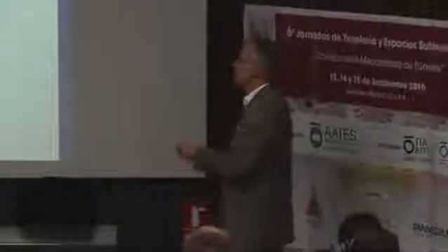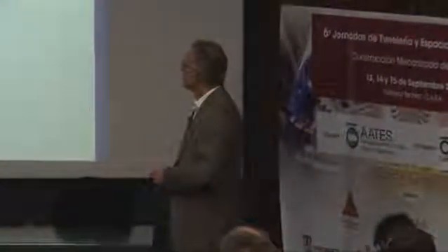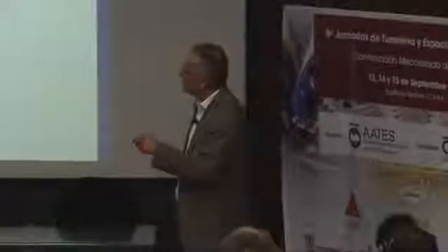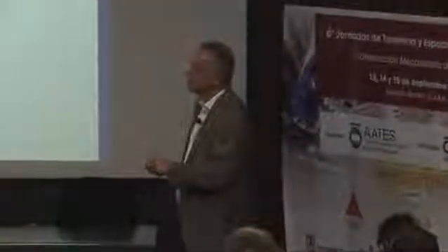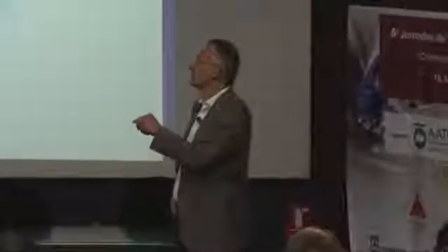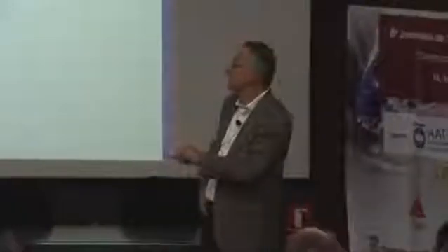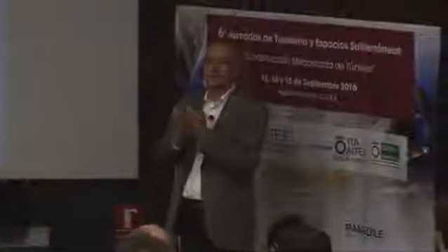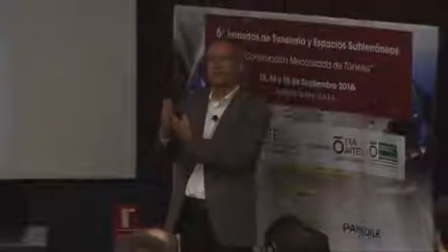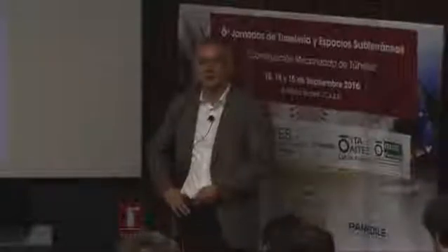So we use a bentonite slurry. We pump it in, as already presented to you this morning, and the bentonite slurry tries to penetrate into the ground as well. The water will disappear into the ground, but it will build up a filter cake, which you can see here on the tunnel face, which finally seals the tunnel face, and that's the point when you can actually apply additional pressure onto your tunnel face.